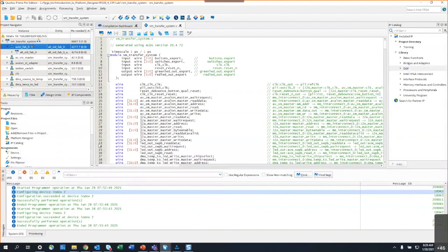It's certainly something that you could try to do, adding false paths. I don't know that it's going to do much, because it will save you timing analysis time, but the wires are still there. The wires don't go away, so it could still affect timing.